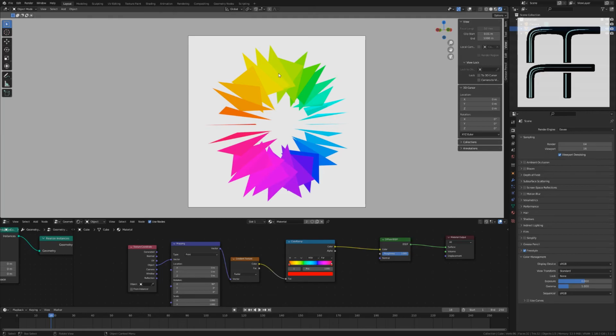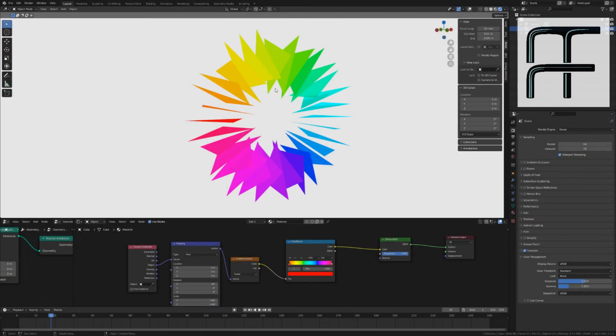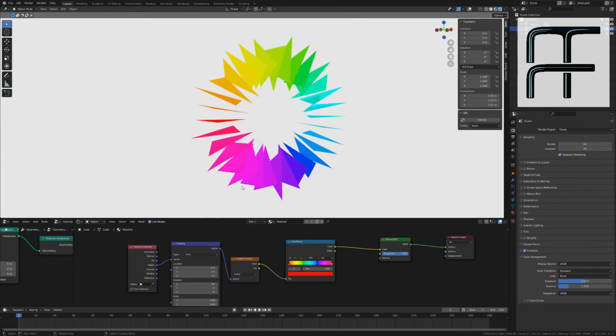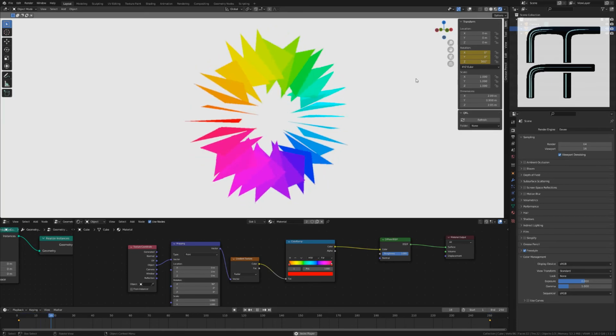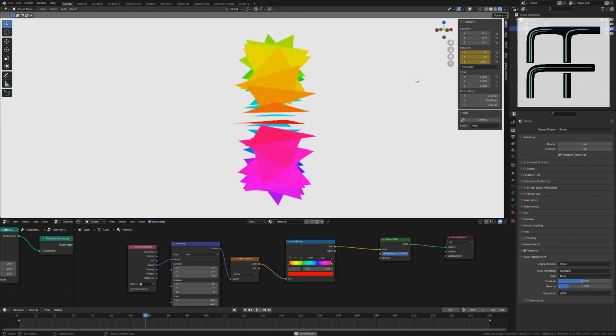From here, the rotating is simple, and so what I did was I took our cube object, took the item, we go back to our first frame, on our rotation set a keyframe on the Z, and we go all the way to the end, and we want to spin it round once, 360 degrees, and set a keyframe again, and that way when we play you can see that that rotates around on its Z axis.